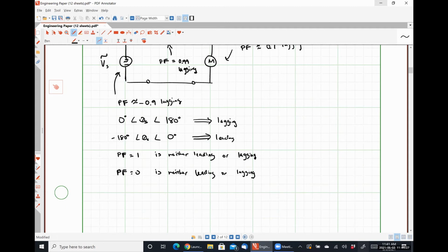The reason why I say that is because while it's definitely got an induction motor to spin, or tumble, the clothes and all that kind of stuff, the heat that's generated by at least an electric dryer is a simple resistive heater, much like you'd see for a space heater, and then a small fan that just blows the heat off of that nichrome wire into the drum to dry your clothes. So heaters typically have a larger average power load because of the way that the heat is generated. If it's a gas dryer where they literally have an open flame and a fan blowing stuff, then obviously that doesn't.